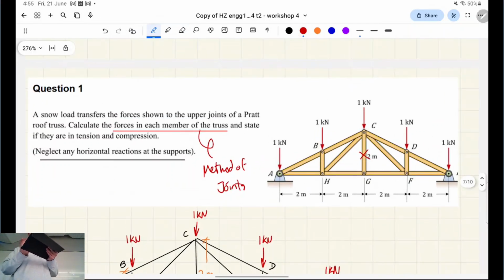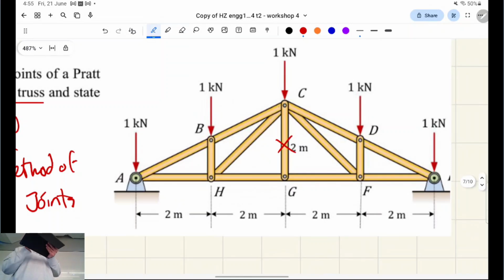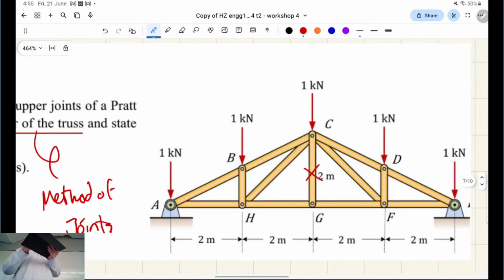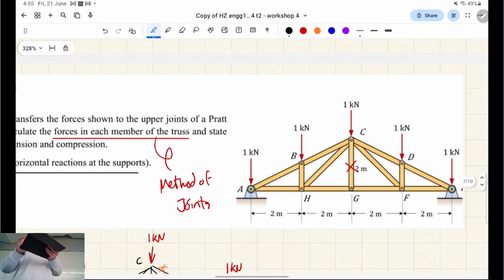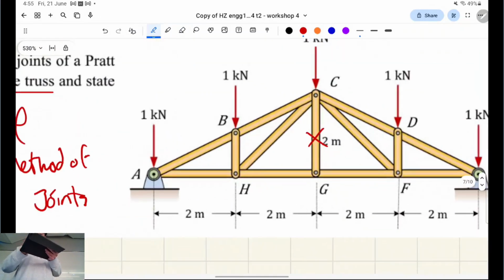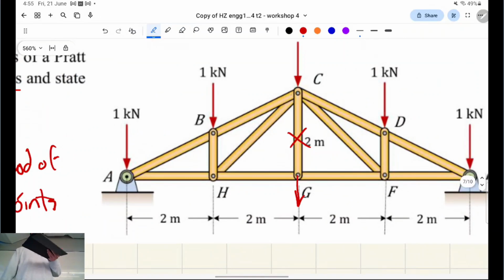Yeah, so we do our analysis of zero force members node by node. So if on one end it's got like a billion truss members connected to it, it can still be a zero force member if on the other end it satisfies that criteria. Nope, because it would be if there wasn't a 1 kilonewton load acting on it. And also, if there was a 1 kilonewton load acting at the bottom pulling this truss down, then this member wouldn't be zero force either, right?